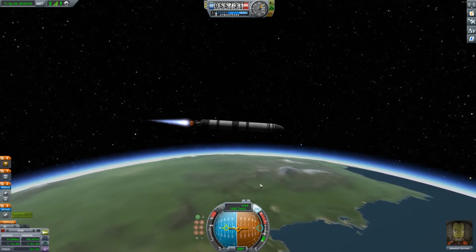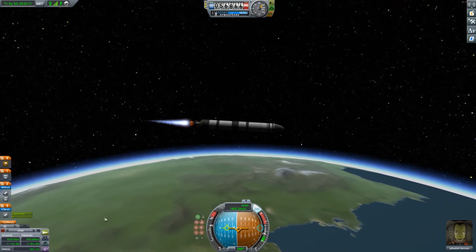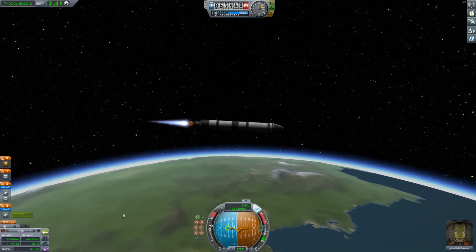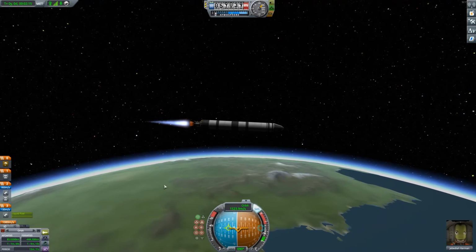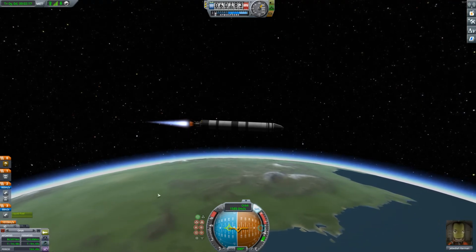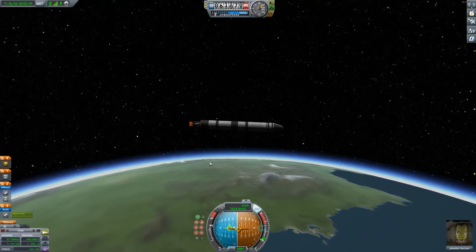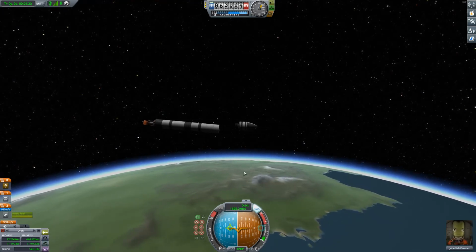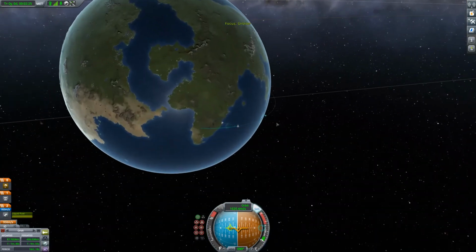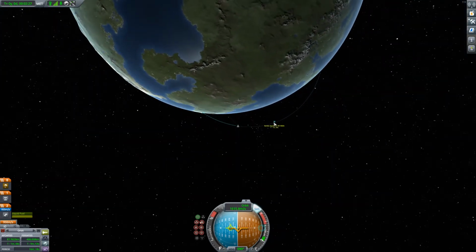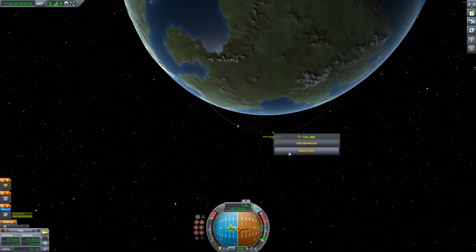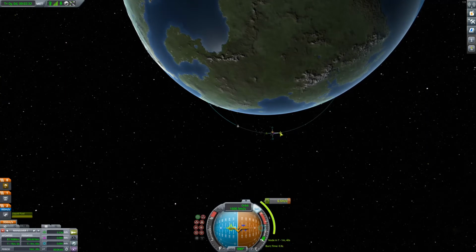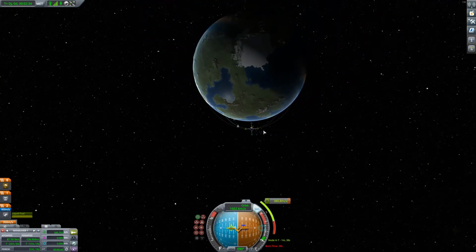So pretty soon we're going to run out of fuel here, and I will jettison the first stage. But I will not light the second stage immediately because we have achieved enough velocity that we can now coast to our apoapsis. As I switch to the map view, we have some time it takes to get to apoapsis. Our apoapsis is going to be at 87,000 meters.